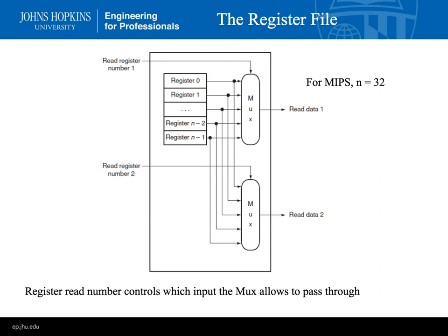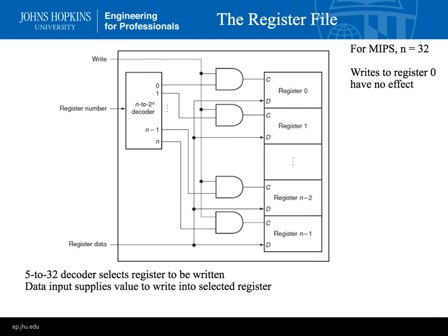And this is what it might look like. So the read register is a choice between 0 and 32, as is this. And then coming out of this mux, based on the choice, would be the read data. Then if we're writing, if the control signal is 1 and we figure out which register number, so if both are 1, we're going to write to here. So this is going to be saying yes, write, and then it'll write the data.